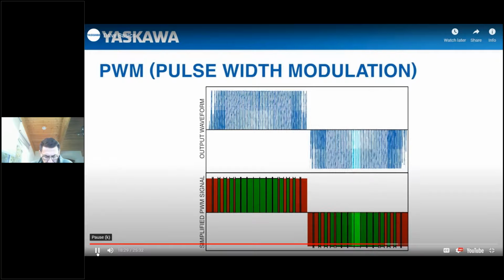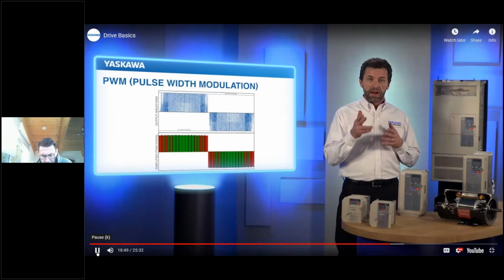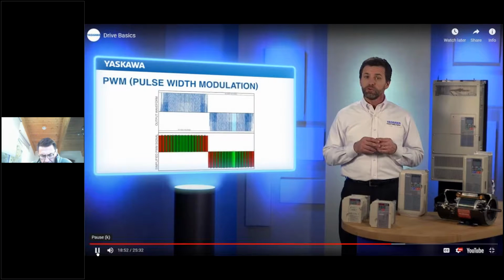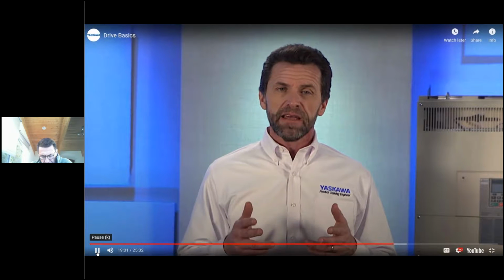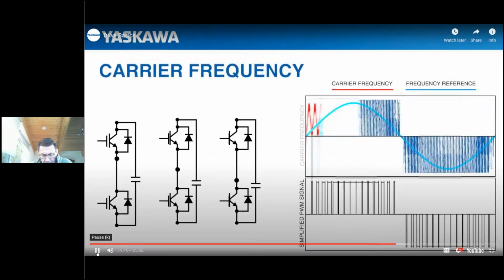You will notice that the voltage waveform is almost square, but is happening in the positive and negative regions. And that's because the IGBTs are pulling from the constant DC bus. Voltage reacts very quickly compared to current, which causes this block-type output. The pulses are high in amplitude, but the RMS, or root mean square, voltage appears equivalent to the motor rated voltage. You will find motors that can handle this PWM style waveform tend to be labeled inverter duty on the nameplate. Now the rate at which IGBT switching occurs is known as the carrier frequency.